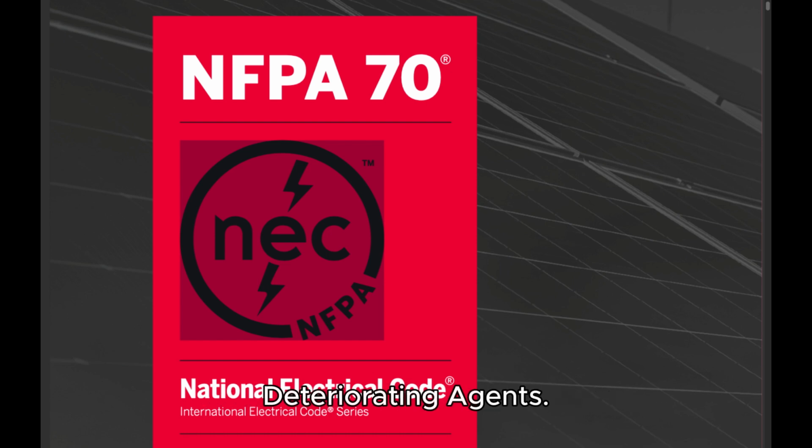110.11 Deteriorating agents. Unless identified for use in the operating environment, no conductors or equipment shall be located in damp or wet locations where exposed to gases, fumes, vapors, liquids, or other agents that have a deteriorating effect on the conductors or equipment, or where exposed to excessive temperatures. Informational Note Number 1: See 300.6 for protection against corrosion.